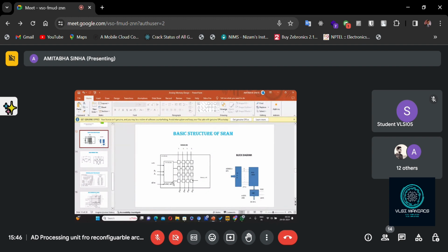That is a mixed signal circuit, because the decoder is digital, and control signals will allow a particular thing to be done. So there also some logic will be used, isn't it? So these cells are analog and these decoders and all are digital. So it is an ideal example of mixed signal circuits.